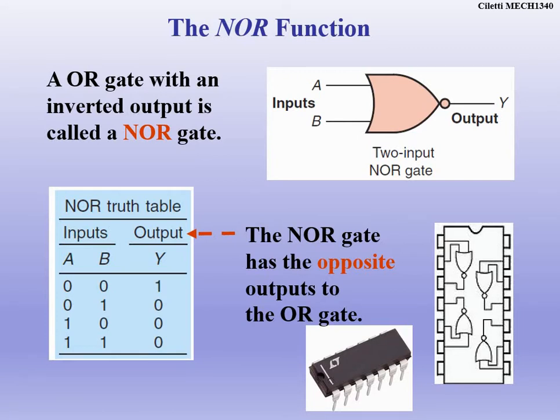And so the picture down here, I didn't talk about on the left side, but that's the logic chip that we would breadboard. So those are 2 input NOR gates. And then remember pin 7 goes to ground, pin 14 goes to VCC. So we can hold up to 4 gates on one chip, and that's assuming that these are 2 input NOR gates.